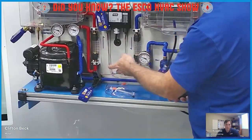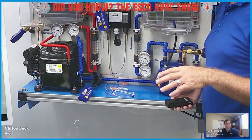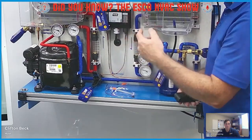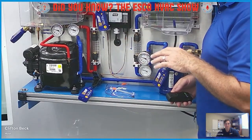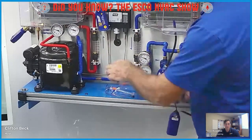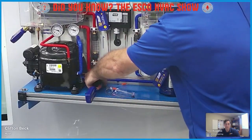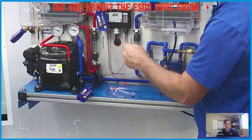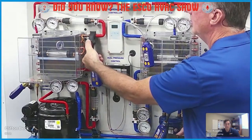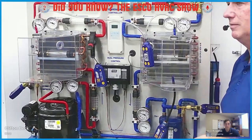Right. So I went ahead and labeled this entire unit. And for instructors, this is a really inexpensive thing for you to do in your classroom on any of your trainers. A simple blue electrical wire loom and red wire loom so that I can mark the low side and the high side of the system. And then I left a section exposed so that I have my bare copper to be able to attach my clamp onto properly. So this particular one is on my low side. And then on my high side, right above it, on the liquid line coming out of that condenser, I've done the same thing with it. And so it's easy to find a good location and keep those visuals, which is pretty handy.